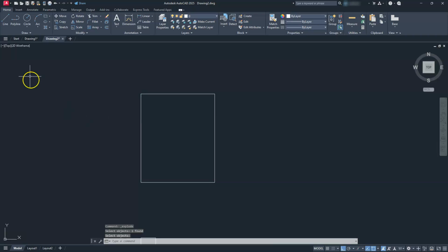All right, so from here, I'll use the offset command. That distance, I look down here on my command line, is already set to 20. So I'll just hit enter. And then I'm going to offset this line going forward this direction. Let's escape out of here.